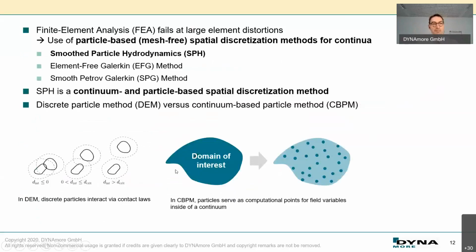Okay, so finite element analysis fails at large deformation. That's why we're going to switch to a particle-based method, or to be more precise, to a mesh-free spatial discretization method. And one of these is the smooth particle hydrodynamics method. Like I said in the introduction, the SPH method is a discretization method for continuum mechanical equations.